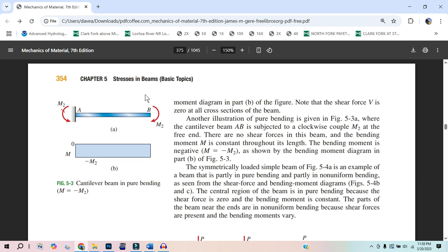And then when we have this segment, we have this moment on this side. So the same rules apply. The beam in outer space would be rolling this way, turning this way. So let's apply a downward force to prevent that. But now we have a net downward force. So we have to have a downward force and an upward force. If we come back over here, this is trying to rotate this beam in this direction. So I must have a downward force and an upward force like this to rotate the beam that direction. And you can see that we're applying a moment. But it is useful to remember that a moment is two opposing forces separated by a distance.